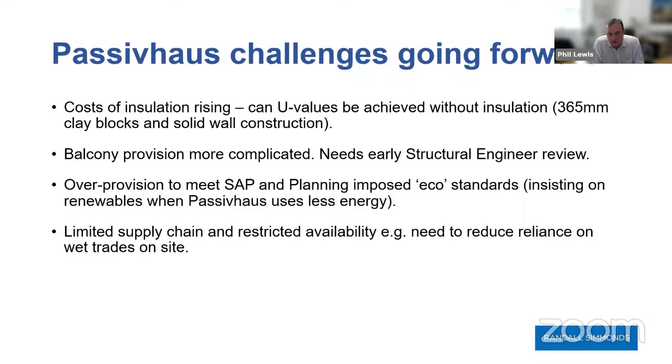Balcony provision is complicated. It needs early structural engineer review. You don't want to create thermal bridging. It's not always possible to have balconies that are self-supporting, and sometimes you get a high steel cost. So you just need to think about those design provisions as you're progressing.